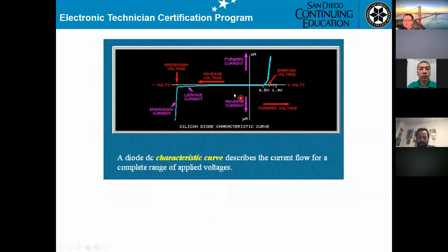If you see the curve, when the voltage equals around 0.65 or 0.7 volt, then the current on the diode keeps going. You see that? But the voltage no longer increases. It stays at 0.7 volt. Current will increase, but the diode voltage does not increase.